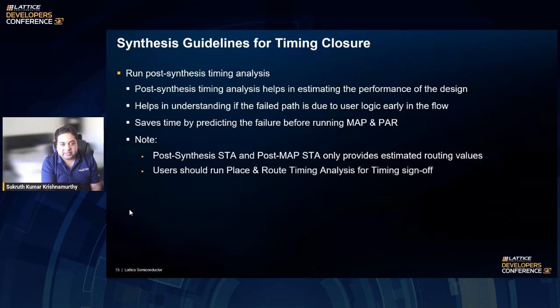On more complex designs, it takes a long time to run map and par, and thus identifying the timing failure at the synthesis stage will save you a lot of time. Also note that post-synthesis STA and post-map STA only provide estimated routing values. Users must always run place and route timing analysis for timing sign-off.